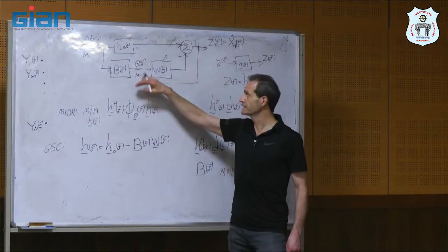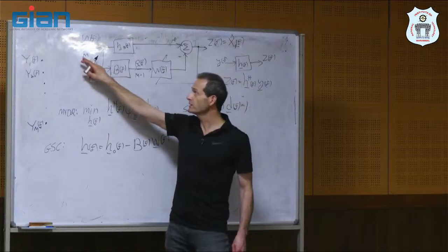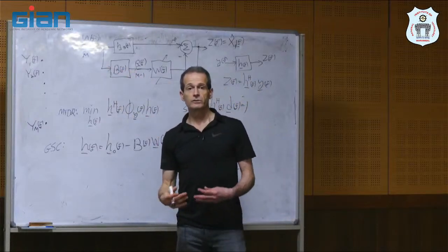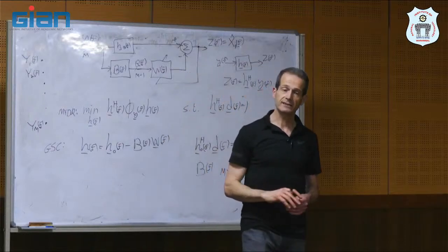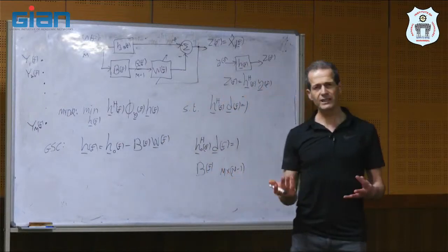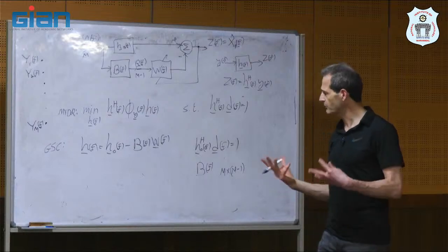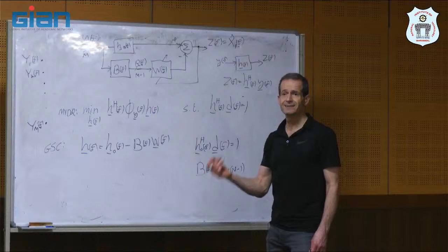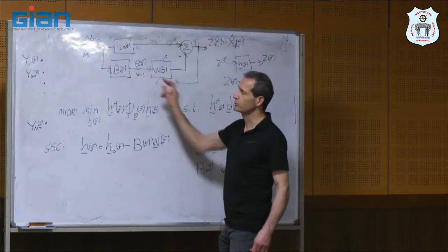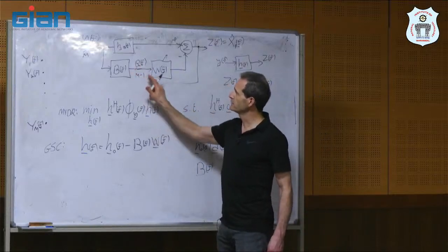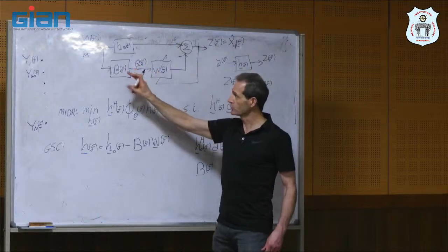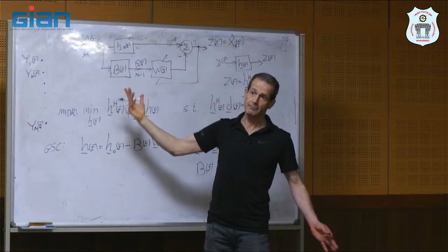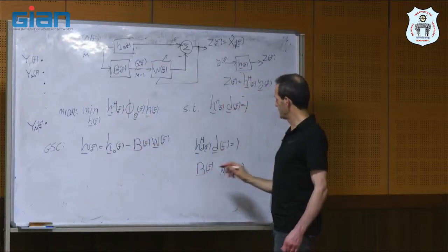Okay, so this is the dimension. We started with M channels. Now we have M minus 1 channels. These channels don't contain the desired signal. So this is the blocking matrix, because it blocks the desired signal at the output. And the maximum number of channels that we can get out of M channels without the desired signal is M minus 1. So this is the blocking matrix.